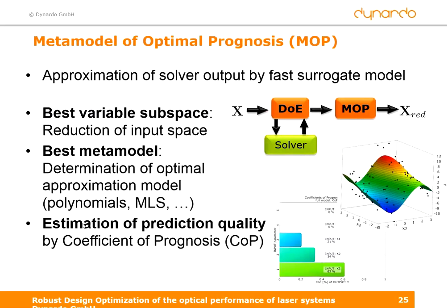And this fitting is estimated with a coefficient of prognosis, which means we have a particular coefficient that really helps you to get models that can also predict points in the design space, like shown here maybe, where no design point has been calculated, but the model is able to approximate it perfectly, which is verified with this coefficient of prognosis.